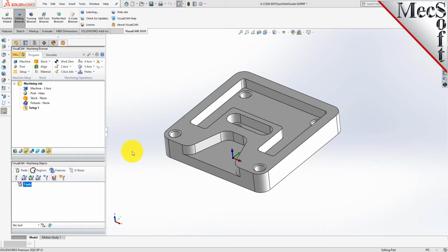Now, there's just two requirements for AFM. The first is that you have to have a solid model. It can be a closed polysurface model, or a solid model that you imported from another CAD application or created. And the other is that you need to have a knowledge base created that has the definitions for each of the toolpaths that your part features contain.